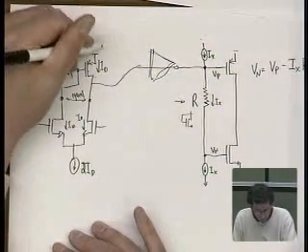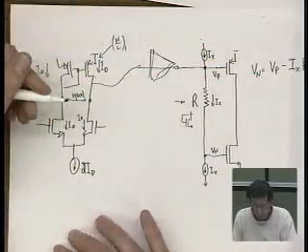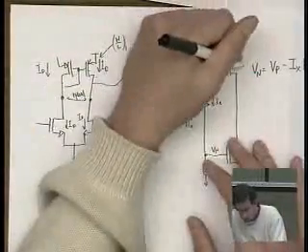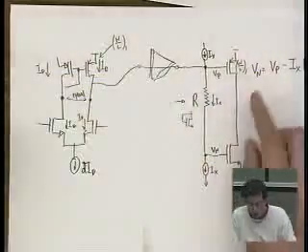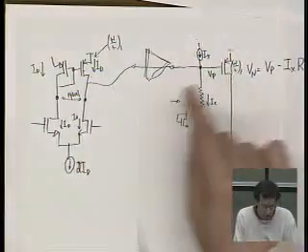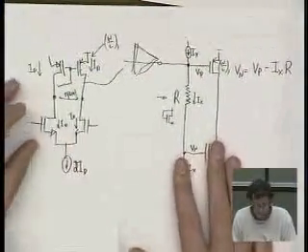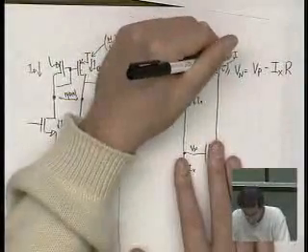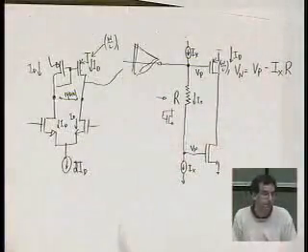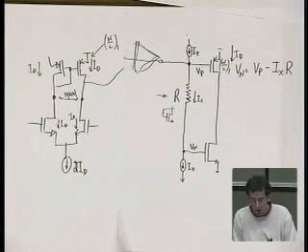So if we put W over L1 on this device, sizing this guy exactly equal to this guy, we know categorically that we'll be sourcing ID here. That's what I went over for design project 1, a way to set up biasing appropriately.